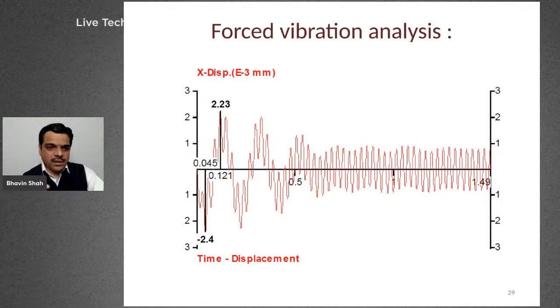If we do not consider a time history analysis and perform only harmonic analysis, then we will only get a response of less than 1 micron in the computer output, and that is going to be a single value. With harmonic analysis, we won't be able to capture the peak value we get in the transient response. That's why time history functions should be considered for dynamic analysis for forced vibration.